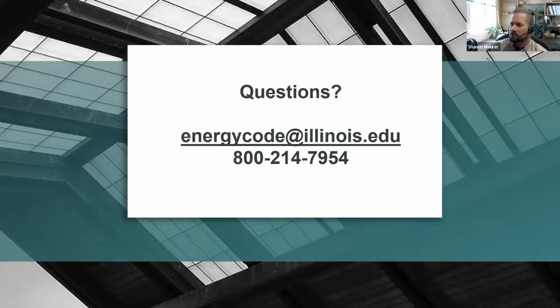Okay, while people are answering those poll questions, let's go back to our Q&A. So we've touched on, are there exceptions for the air leakage test of commercial buildings? Yes, there are, but none of them apply to climate zones 4 and 5A in Illinois. So for Illinois projects, all buildings will have to be pressure tested. All new buildings. Yes, new buildings.